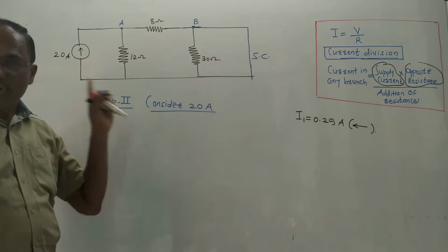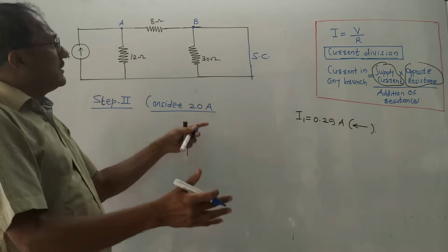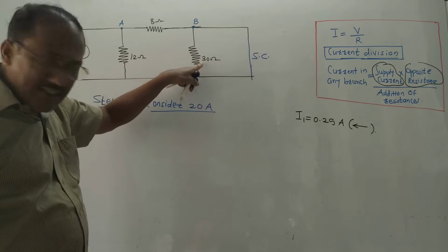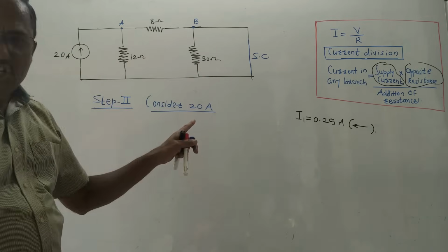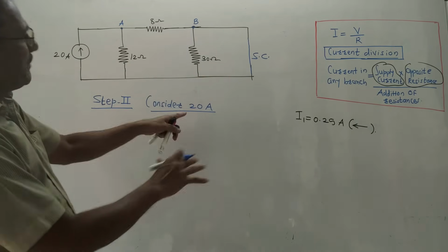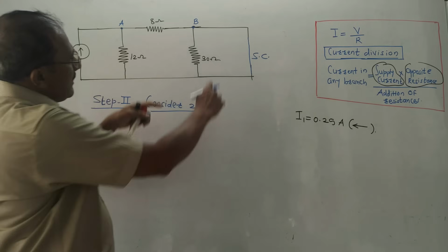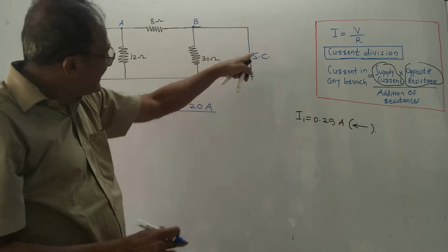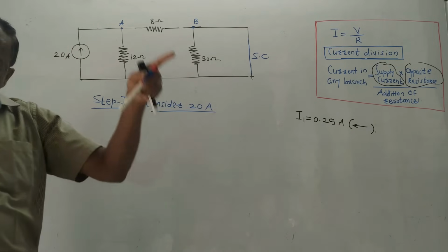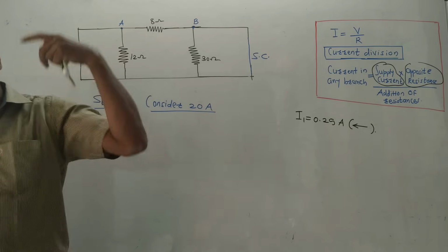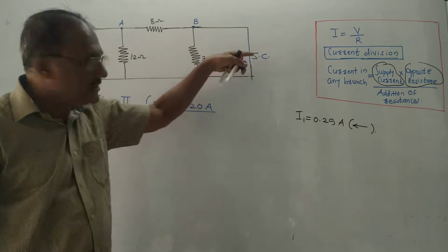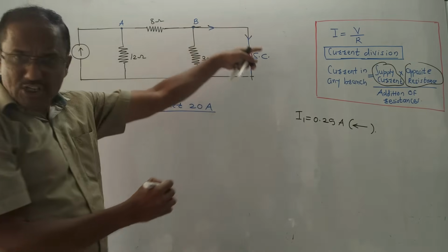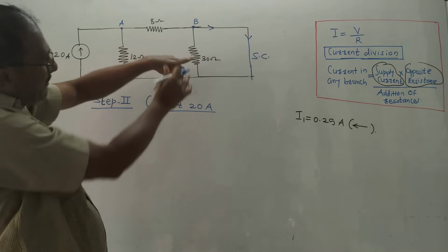Now one very important concept. Do remember, throughout the calculation, if a short circuit is there in parallel with any branch, then that branch will become inactive. I will repeat. This is a 30 ohm resistance. There is a parallel branch which is simply a wire. No resistance is over there. This is called a short circuit. The tendency of current is always to flow through the path which has minimum resistance. Short circuit is zero resistance. So whatever current is flowing, the entire current will pass through this short circuit branch. No current will pass through the earlier branch, that is through 3 ohm.